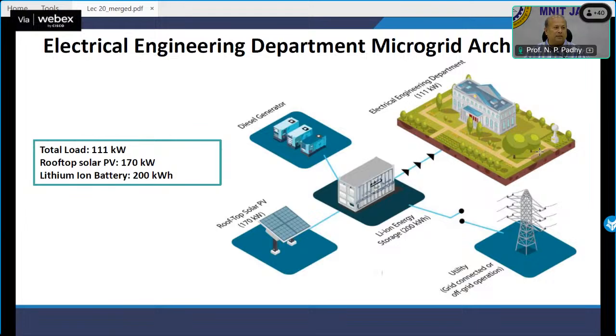Probably it is 80 to 85% efficiency. So even if it is giving 150 or 140, I have 30 kilowatt excess, and for 7 to 8 hours, it is close to 200 to 220 kilowatt hour. So my battery is efficiently working. Very rarely do we derate.